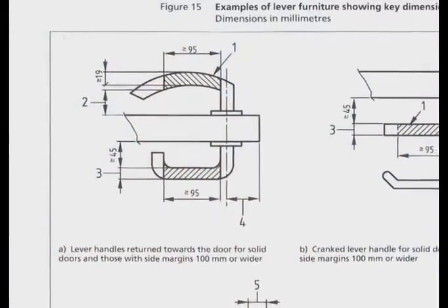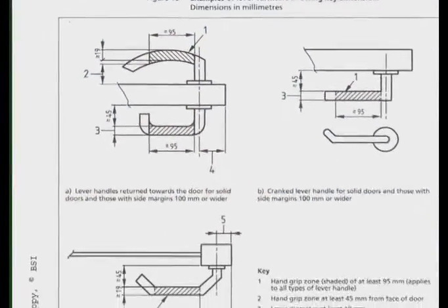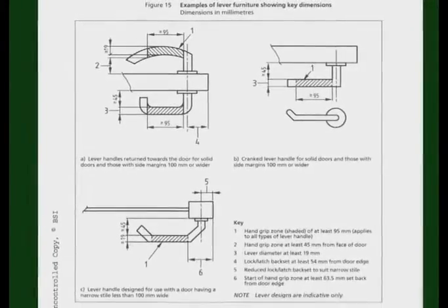Yeah. Now, on door ironmongery, it says it should be possible to operate all door-opening furniture one-handed without the need to grasp or twist. Now, what's the implication of this? The implications are that the standard pretty much recommends that knob-type furniture shouldn't be used, or small thumb turns. And basically because they're very difficult to operate by people with limited dexterity or arthritis or a weak grip. So whenever possible, lever-type furniture should be used. OK, so it limits the sort of door-closing furniture that you can use.